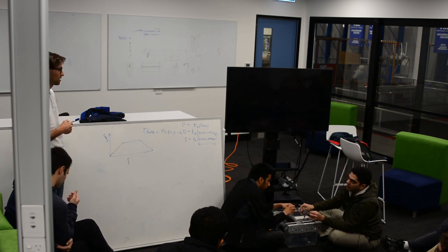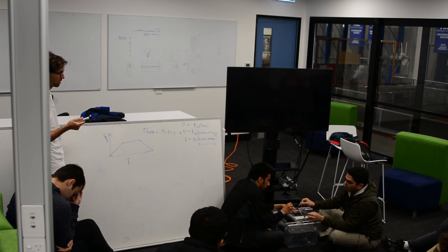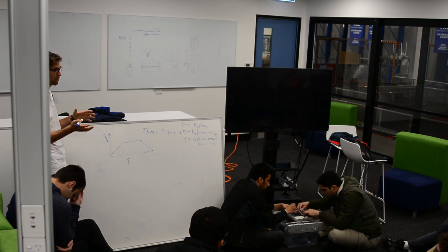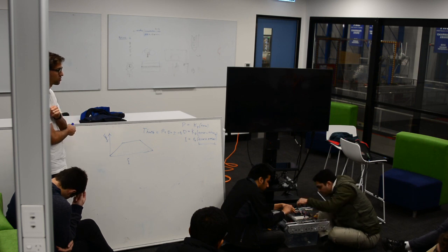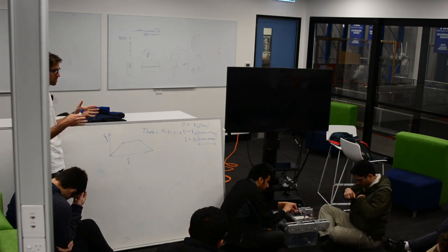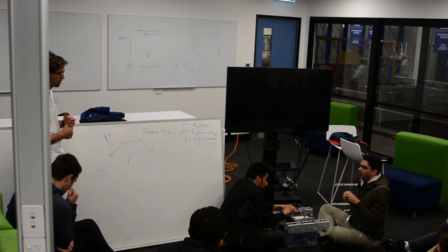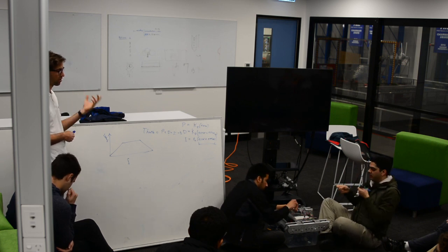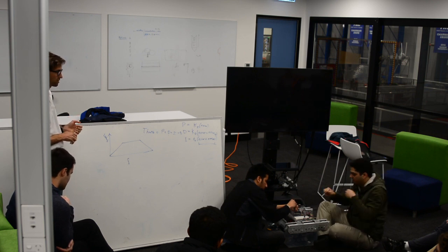You could check 10 times a second or 100 times a second and ask how many pulses went past. Then you could say that 100 pulses went past in the last 10 milliseconds. But I think it's harder to do that across a range of motors and things like that. There are speed sensors that produce analog voltage for speed, but I think I would try to do a lot with position control.